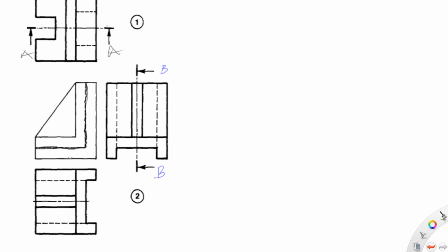Now we need to isolate the areas we will not hatch. We know that from the back through the bottom there is void. So in that case we are going to ensure that we isolate the void. So here there is void throughout, so here we don't hatch it, so it should be plain. Then this is a web, the web too, we don't hatch the web. So the web is isolated. We don't hatch the web, we don't hatch the void around the object from the back and the bottom.